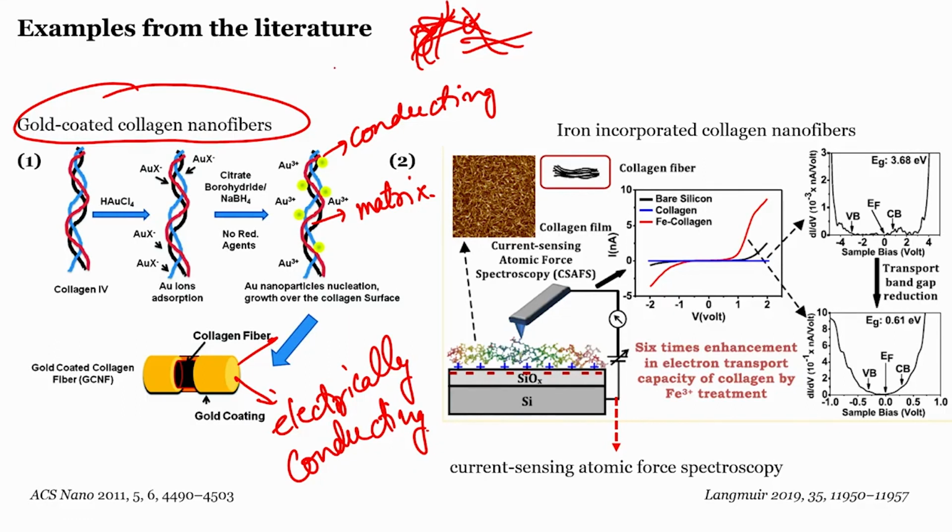what would one try to deduce given the discussion that we have been having? The most important conclusion that we would have is there is no direct contact between these two gold nanoparticles, though they are very closely situated, mostly in terms of few nanometers. There is no direct contact. So what kind of transport would be happening? Yes, it would be percolative transport, and that's what was reported in this work,